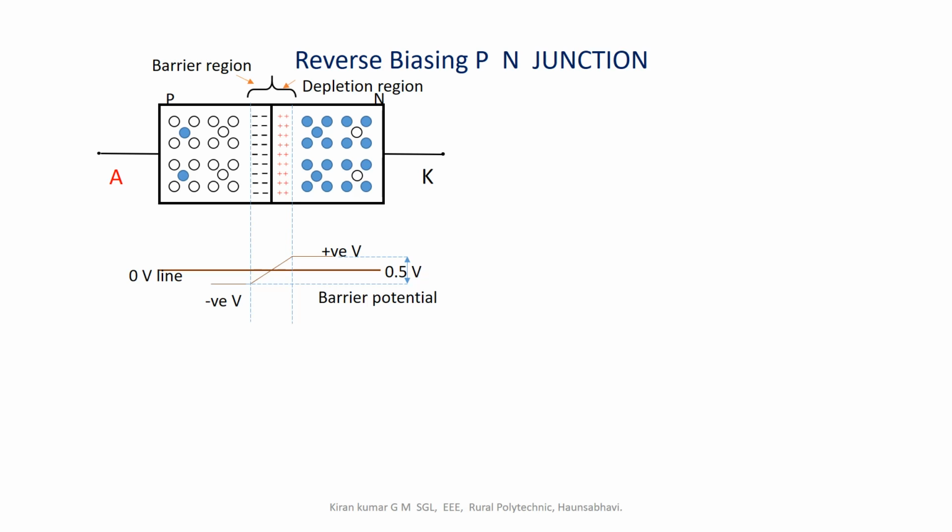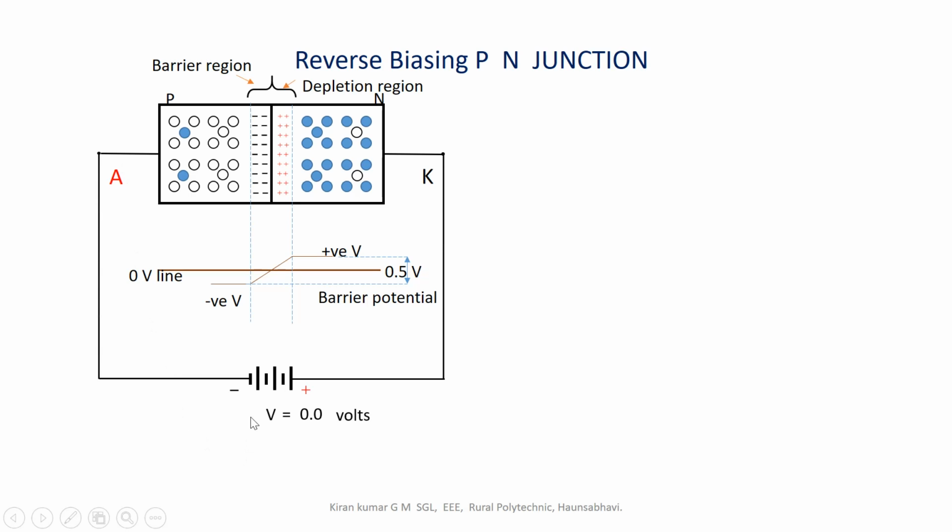To make the PN junction reverse biased, the anode of the diode has to be connected to the negative terminal and the cathode of the diode has to be connected to the positive terminal of the external battery as shown in the figure. The behavior of the diode with the application of reverse voltage across anode and cathode, and the reverse current which is possibly flowing in this diode, is observed by plotting the two variations in the negative two-dimensional axis here.